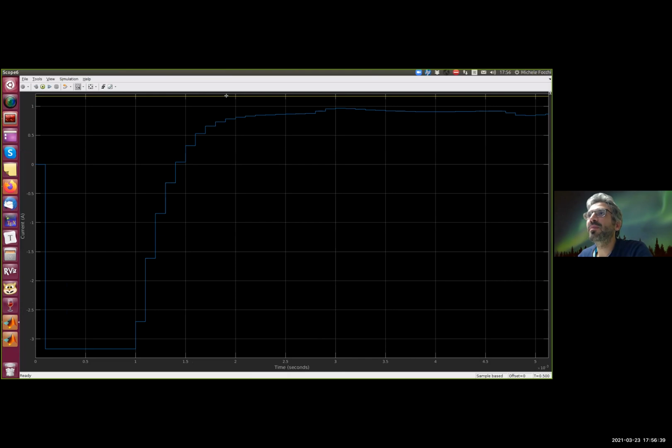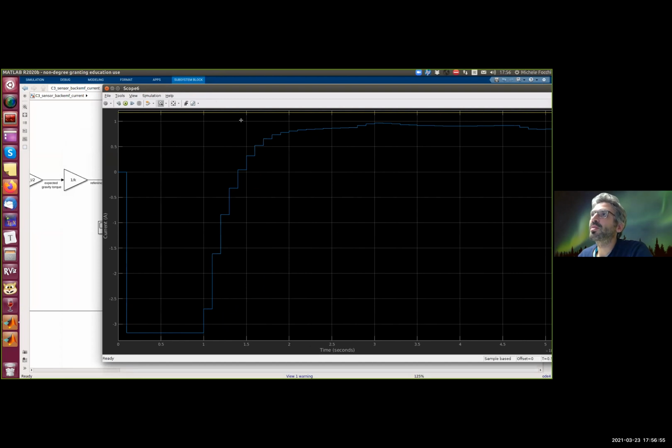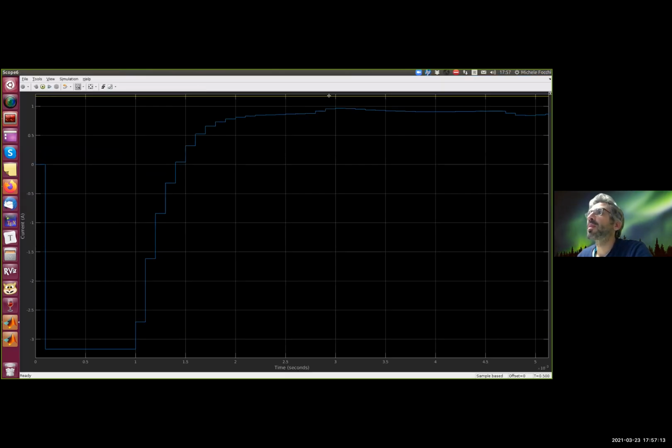And you remember you need to get first the delay of the system, and then you need to get the intercept between this approximation, this tangent to the flexus that is here, and the intercept is around 1.29. And then the gain is the steady state value. In essence, the gain is the steady state value divided by the input we gave.